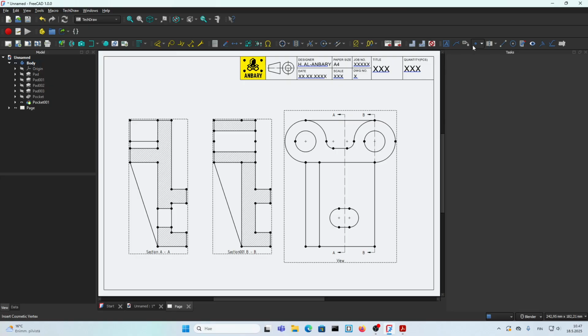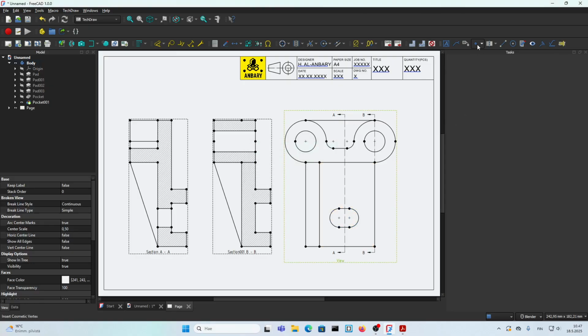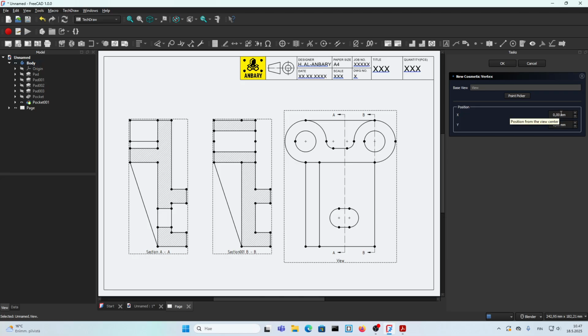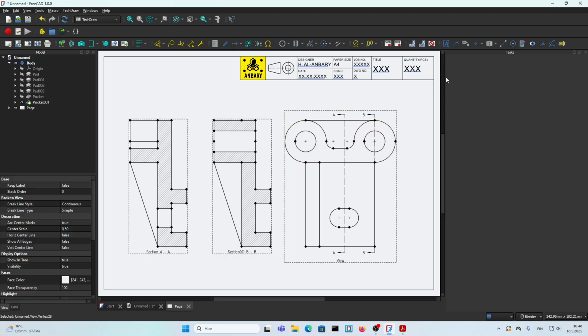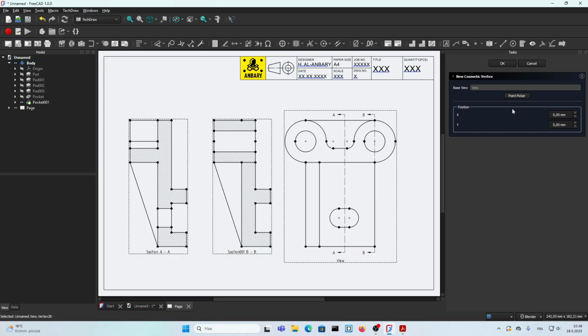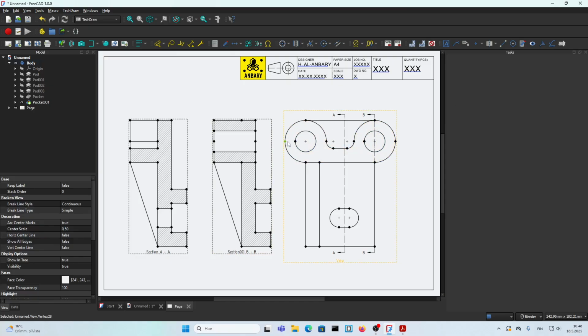Now onto the other side, same thing. Choose the view, insert a point, and Y, you have to put now negative 36, negative 48, negative 48, like this. It went wrong. Let's delete this. I did something wrong. From here, X negative 48, and this one, sorry, this one stays positive 36. That's where the error is. And now I have these two dots, and I can put my dimension like this.